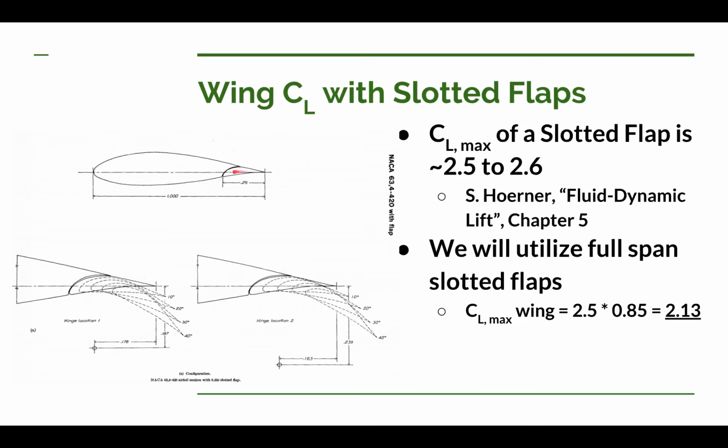So at normal cruise then, we should not have any air flowing through here, causing a disruption of our boundary layer and thus increasing drag. So that's another potential advantage of the slotted flap, as long as we do a good job of fabrication. But we also have a disadvantage, and that's because of having to hinge the slotted flap far below where our wing is. With the plain flap, our hinge is built inside the wing. But with the slotted flap, our hinge has to be down below.